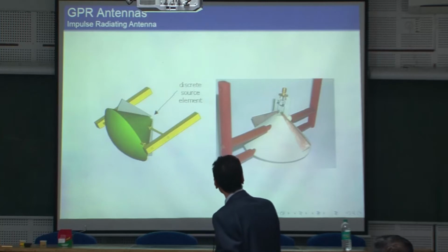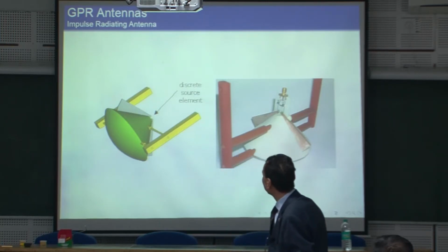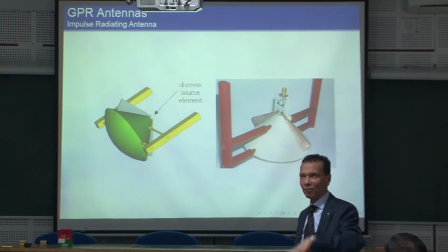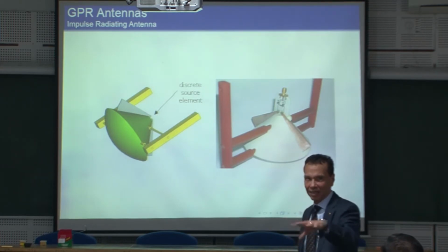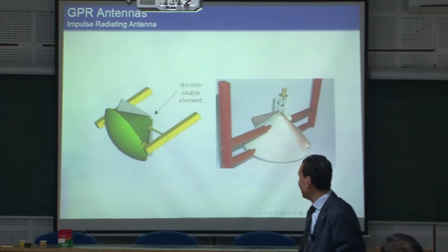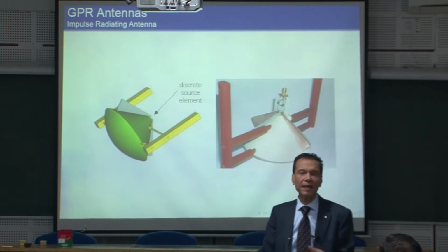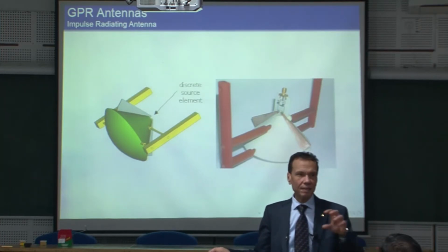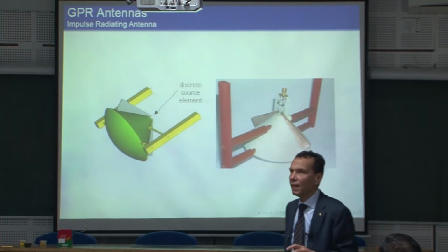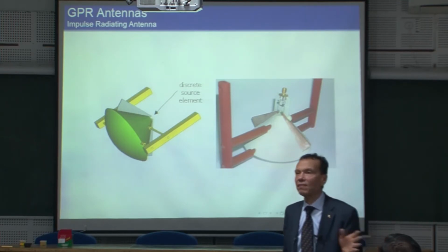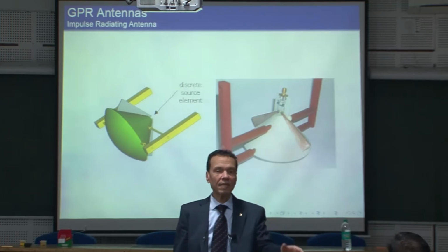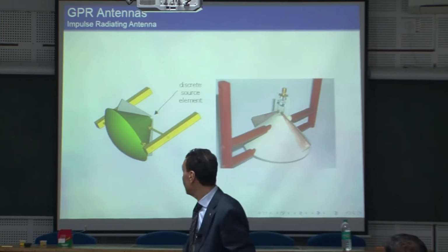Okay. This is another type of wideband antenna, because as I told you before, we need the wide bandwidth for the penetration. And afterwards we have such antennas here. They are not directive. Important here is the wide bandwidth, especially if you would like to cover the bandwidth over different waveguide bands, say X band, Ku band, and so on.